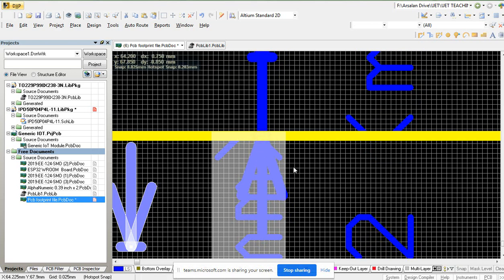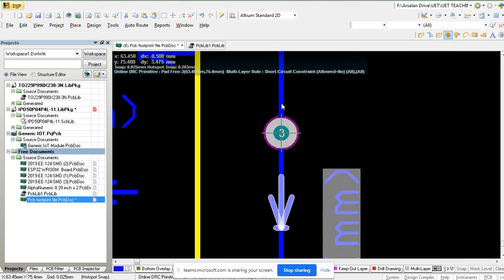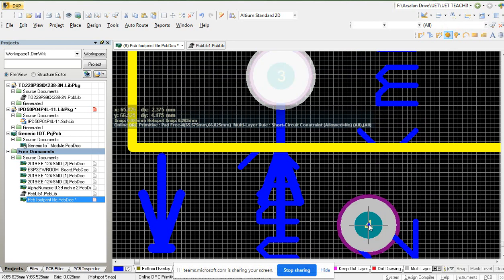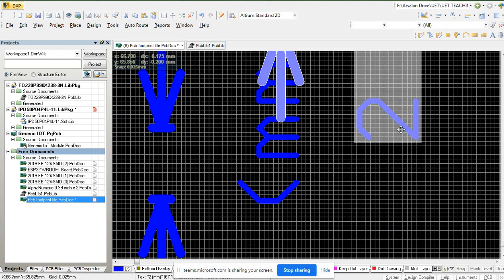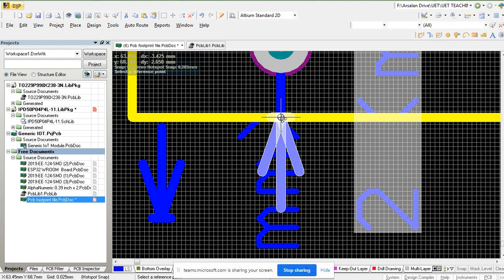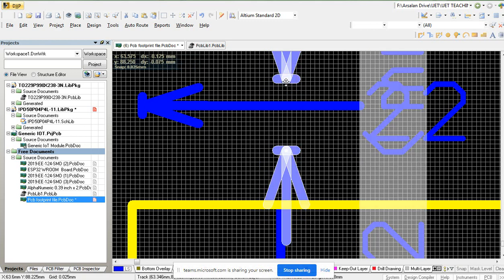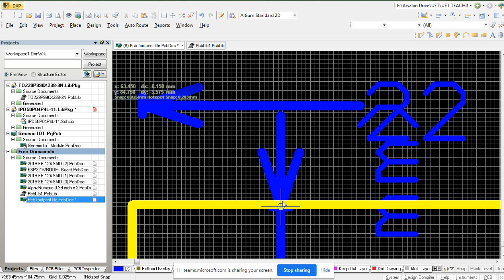so this is my 2 mm line, and now since this is selected, I can take a pad and this is placed. Okay, so I will just take another 2 mm, just copy this one, so this is copied, and okay, this one, the direction is opposite, don't worry about that part, and I will just place it.